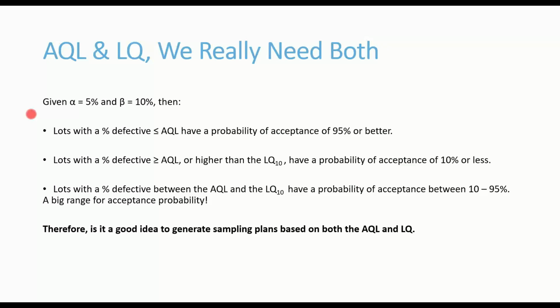So to select a statistically valid sampling plan, first, the objective of the inspection should be determined based on past performance, maybe other controls that are in place, potential failure modes, and so on and so on. You could probably think of some other things, right? Then the AQL and the LQ of the sampling plan should be documented. We document everything, right, to determine that the sampling plan meets the objectives. And further, since different sampling plans may be statistically valid at different times during the life of a process, all sampling plans should be periodically reviewed. So you want to have a schedule of review for them.